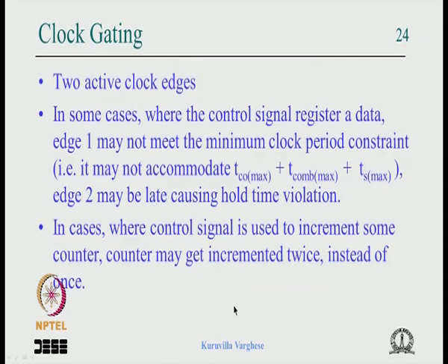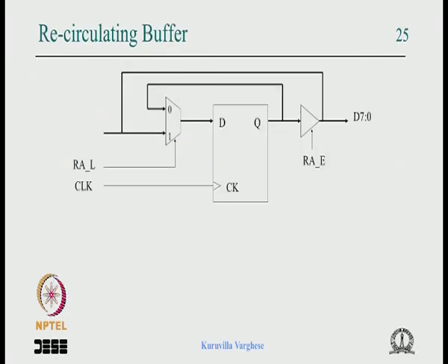Okay. So that is why I have discussed these points, that is why we have looked at this scheme. When we discussed the CPU, I showed this scheme, and this does not have the timing disadvantage. Here we are not doing anything with the clock path, we are combining the latch signal in the data path. It has advantage in 2 ways. One is that when the latch is 1, the input is going there.